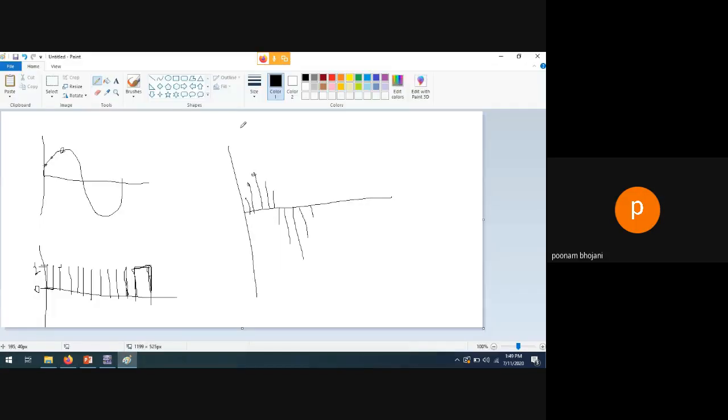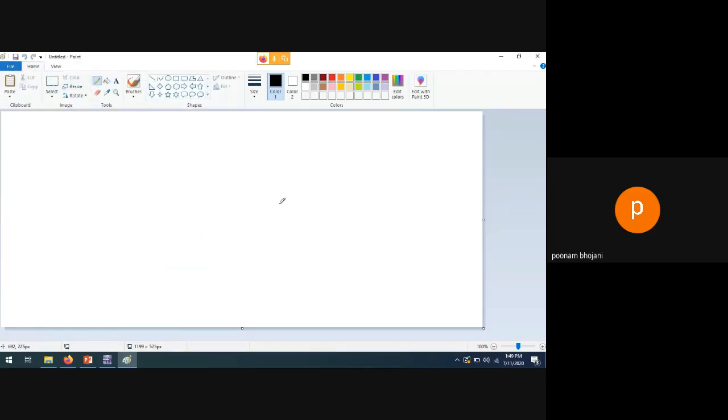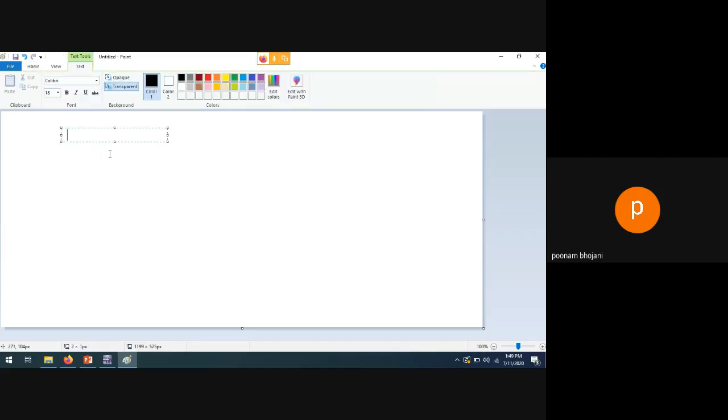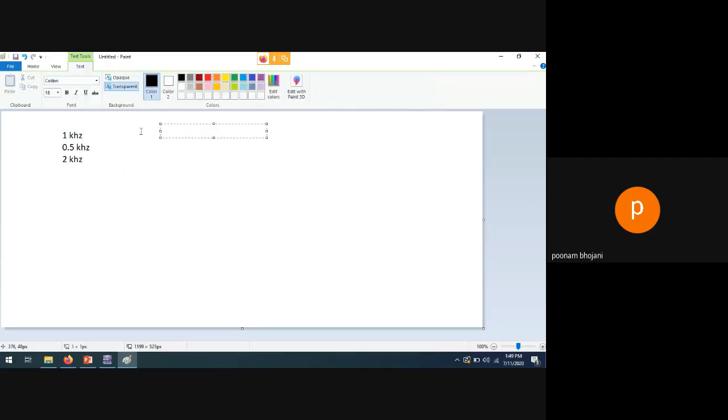No, let me tell you, Arafat. I understood where you are facing this confusion. I am saying that if you take, let's say, a composite signal, one of 1 kilohertz, second of 0.5 kilohertz, and third of 2 kilohertz. Just a minute. What will be the Nyquist rate for each signal? For 1 kilohertz, the Nyquist rate will be 2 kilohertz. For 0.5, it will be 1 kilohertz. And for 2 kilohertz, it will be 4 kilohertz.